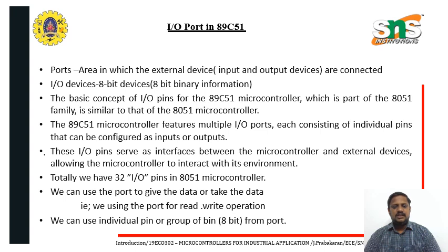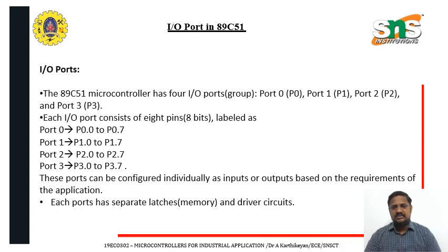In total, 32 I/O pins are available in the 8051 microcontroller. We can take in data or give out data, so we use them for read and write operations. Those are the main operations of the I/O ports of the 89C51. There are port 0, port 1, port 2 and port 3, and each I/O port consists of 8 pins, numbered 0 to 7.